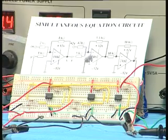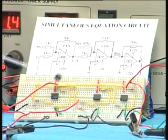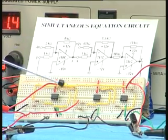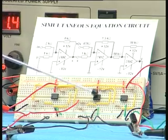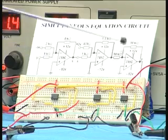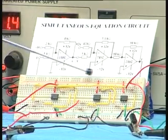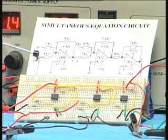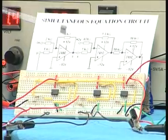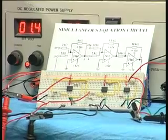So this is an actual circuit wired with the 3 op amps as seen here. This is the first op amp that you have here. You have got the 1k and the 2k and the feedback resistor, all those things, and this is the second op amp here, and you have got the 470 ohms and the 1k and the feedback resistor 1.5k, and the last one is 10k with the feedback resistor 10k, an inverter, and the output of that is brought all the way and given at the input corresponding to y. So this is precisely the same circuit which I have wired, and I wanted to measure the voltage here.